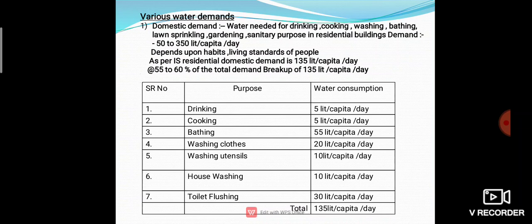In the first section we studied how the rate of demand is calculated. Then rate of demand is dependent on the second factor, population. The persons to be served by the scheme are calculated, and an estimate of future population is worked out by suitable methods.